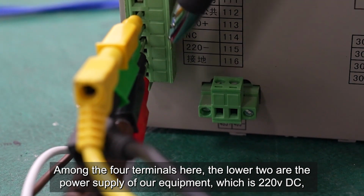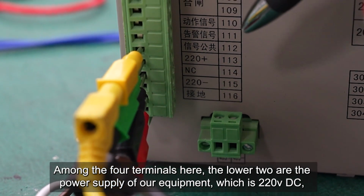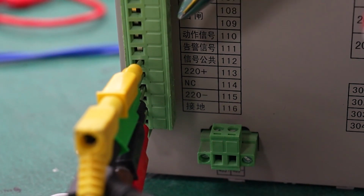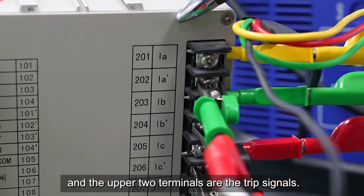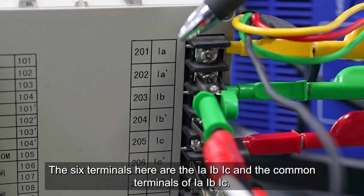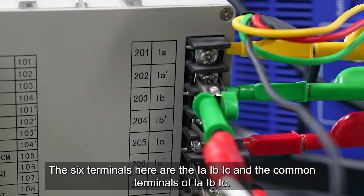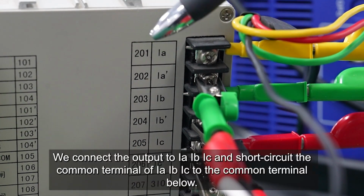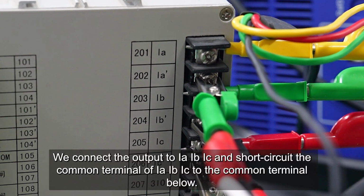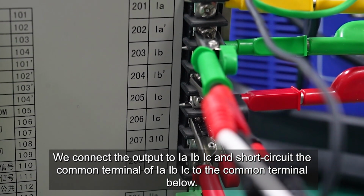Among the 4 terminals here, the lower 2 are the power supply of our equipment, which is 220V DC, and the upper 2 terminals are the trip signals. The 6 terminals here are the IA, IB, IC, and the common terminals of IA, IB, IC. We connect the output to IA, IB, IC and short circuit the common terminal of IA, IB, IC to the common terminal below.